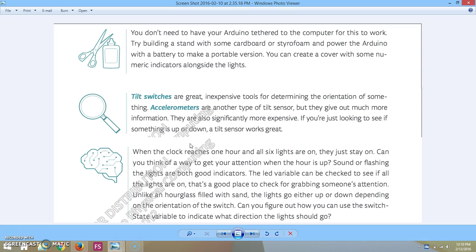The resistors would matter more in a portable version of this chapter, because a battery has a limited amount of power we can use, and if we use the 220 ohm resistor on the tilt switch, we would be wasting more current or power, which we could use for extra parts. For example, when we finish lighting up all the LEDs, we could add a speaker to make an alarm, or we can put in extra LEDs as an indicator that all 7 LEDs have turned on.